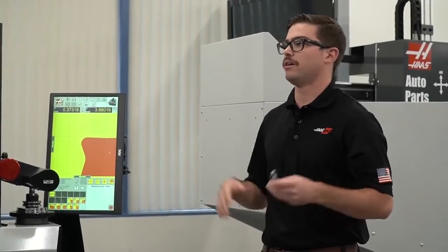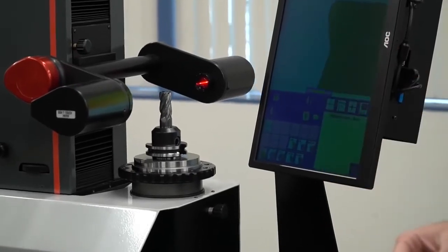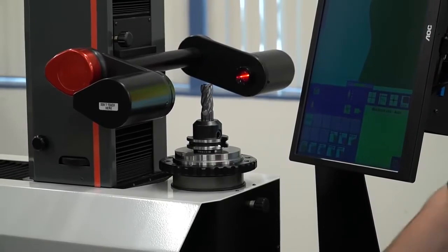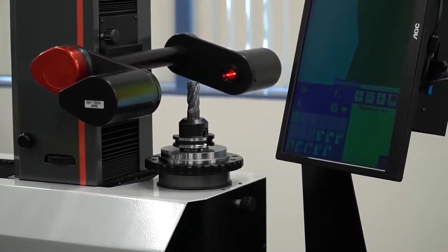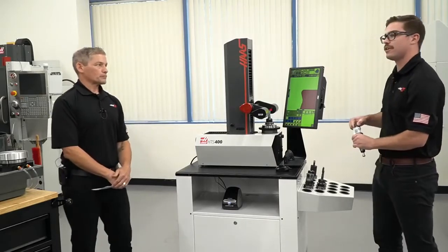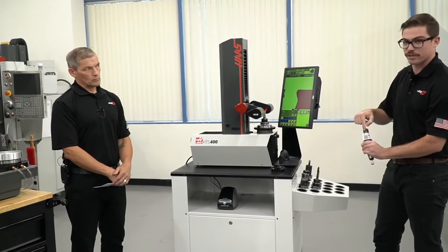You can do this on both NGC and the classic controls, so you don't have to worry about whether your control works. Uploading an offset file works for both newer and older machines. Okay. Right. And then there's a third way. Yeah, and this is one of my favorites. This is exclusive to NGC controls. When I create my tools and send my offsets, I can actually print out a label with its QR code.